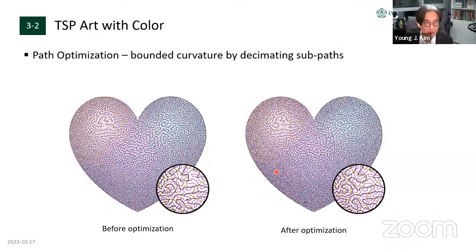Now, the final step is that you can use this path for robot trajectory following. But again, if you look at the created path, it's quite jagged. It also has very sharp corners and many stippling points, which is not very good for the robot end effector to follow, because you need high acceleration to stop, move, and go in the other direction.